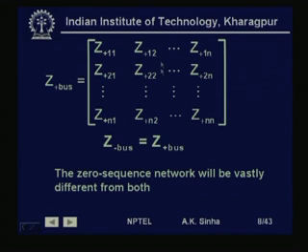Same way we can build this matrix for the negative sequence as well as the 0 sequence. In general, the negative sequence matrix and positive sequence matrix are considered to be the same, because the only elements where we find that the impedances will be somewhat different are the generators as well as the loads, where we may have induction machine loads.